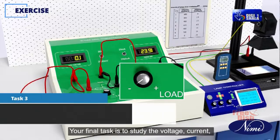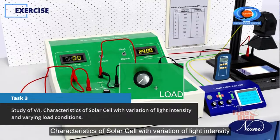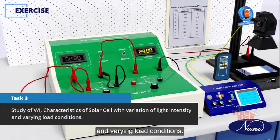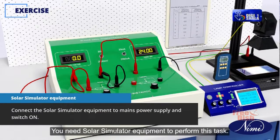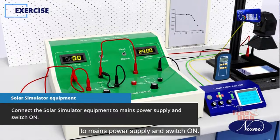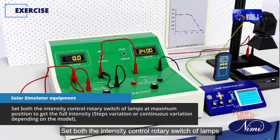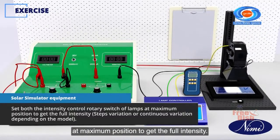Your final task is to study the voltage-current characteristics of a solar cell with variation of light intensity and varying load conditions. You need solar simulator equipment to perform this task. Connect the solar simulator equipment to the mains power supply and switch on. Set both the intensity control rotary switches of the lamps at the maximum position to get the full intensity.